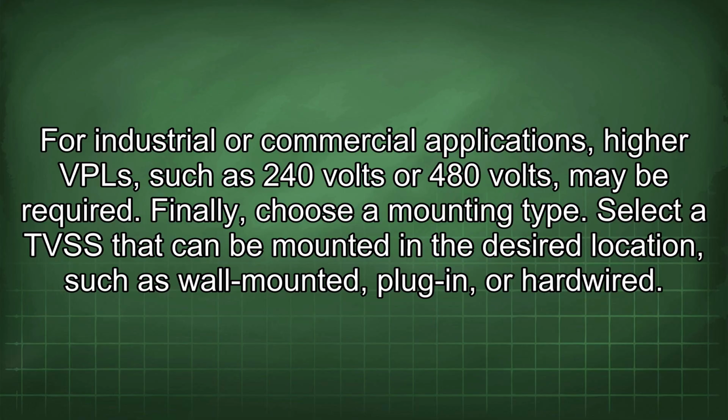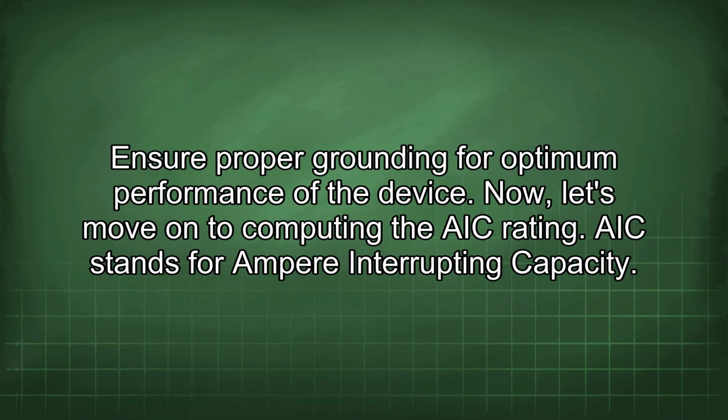Finally, choose a mounting type. Select a TVSS that can be mounted in the desired location, such as wall-mounted, plug-in, or hardwired. Ensure proper grounding for optimum performance of the device.